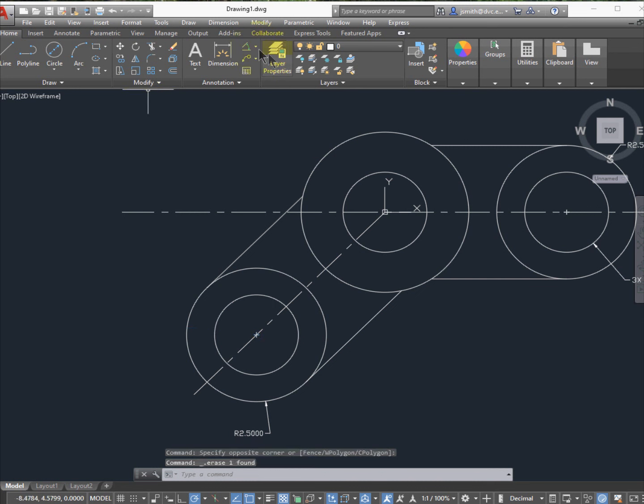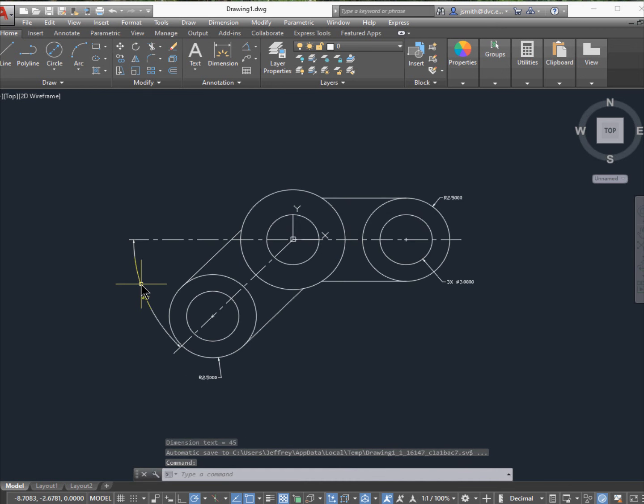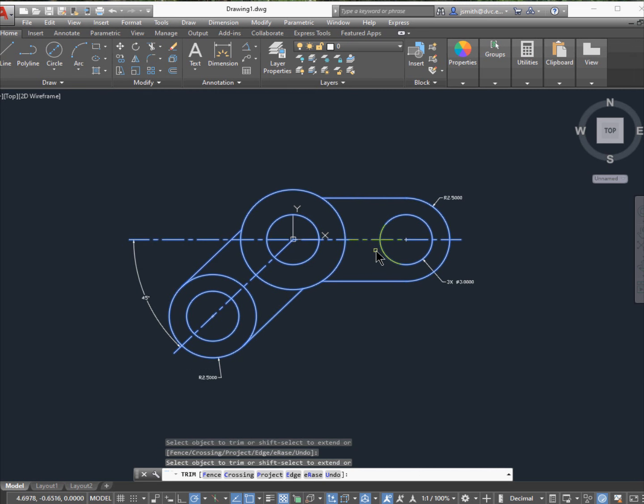And I'm looking at my drawing on my PDF file. So I'm going to try to copy that. And I'm getting rid of some items that I don't need here. But now what I can do is go ahead and dimension this angle, or make the annotation that's 45 degrees. And that looks good. Okay, so far so good here.